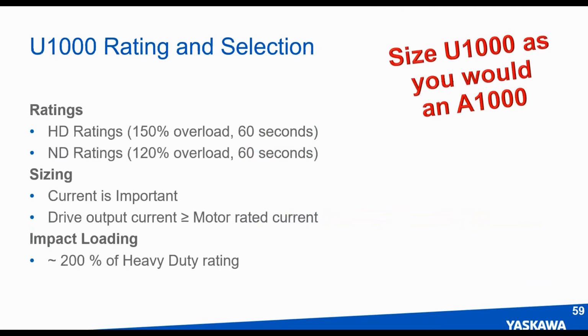So how do I size the U1000? Well, just like an A1000. The U1000 has normal duty ratings and heavy duty ratings. Unlike regular drives that have to focus on power and current when they size their drives, the U1000 need only be sized based on its current rating.